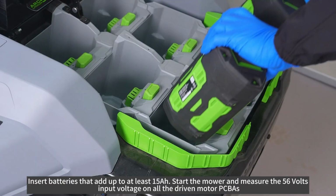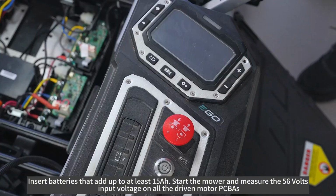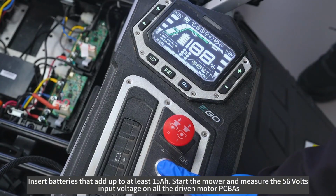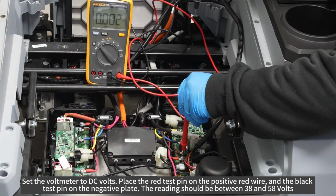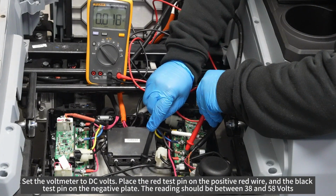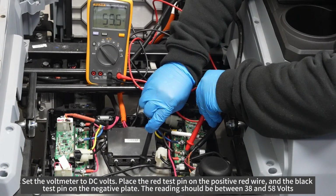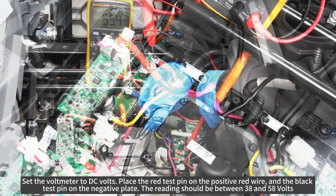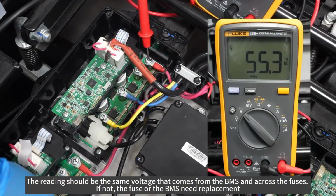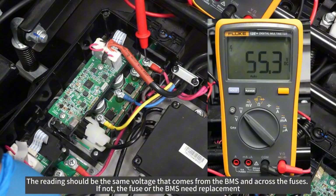Insert batteries that add up to at least 15 ampere-hours. Start the mower and measure the 56 volts input voltage on all the drive motor PCBAs. Set the voltmeter to DC volts. Place the red test pin on the positive red wire and the black test pin on the negative plate. The reading should be between 38 and 58 volts. The reading should be the same voltage that comes from the BMS and across the fuses. If not, the fuse or the BMS need replacement.